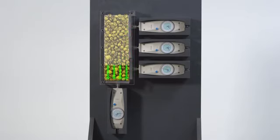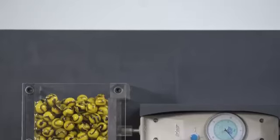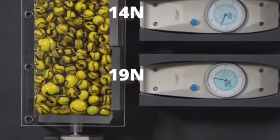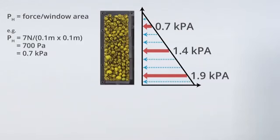Using this information, we can determine the horizontal pressure distribution along the side of the chamber and the vertical pressure at its bottom. When the chamber is filled with marbles, an example of a granular material, the indicated horizontal forces are 7, 14, and 19 newtons. And the downwards force on the bottom window is 33 newtons. And it is easy to see that the corresponding horizontal pressures do indeed increase linearly with depth.